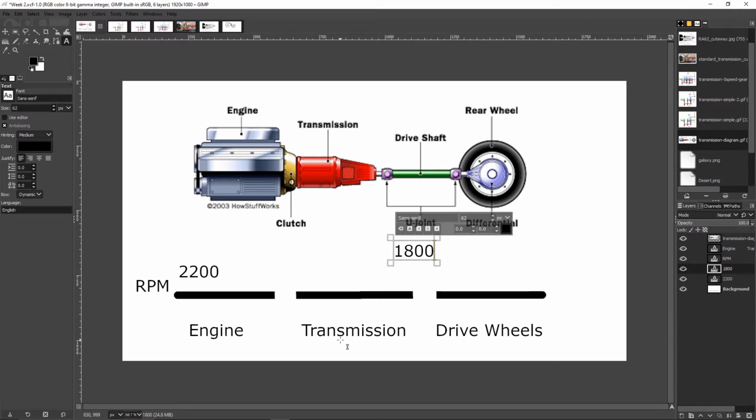This is fifth gear, sixth gear. And when we had situations where the gear ratio was high, like 4.1 to 1, first gear, we're sacrificing distance for torque, right? Torque multiplication, but it won't go nearly as high on top end. That would be an underdrive, and then we hit direct drive where it'd be 1 to 1, and then any overdrive is this.